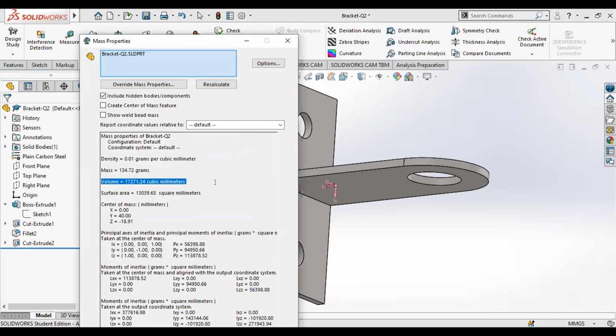But the density of the material we have to key in is a mass value, right? Okay, if you're not looking for the mass, even if you put in the wrong value, never mind. Oh, the density will not affect the maximum yield strength, right? No, it won't even affect. Because for the calculations, the stress is the force divided by the area. So the input doesn't have a density. So it doesn't matter.